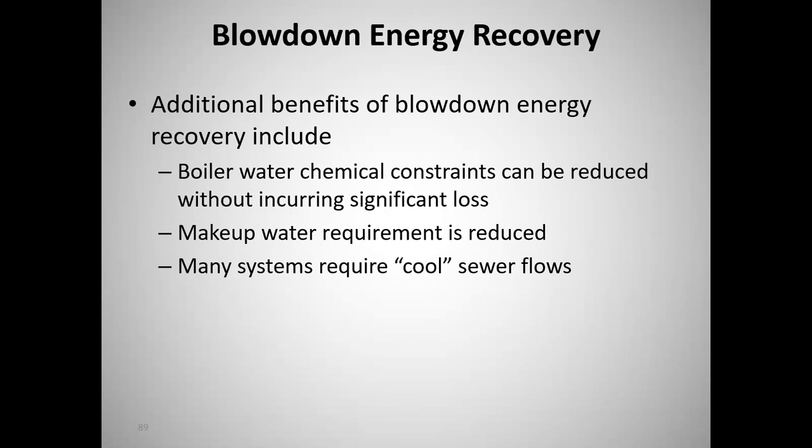Additional benefits from blowdown energy recovery include that boiler water chemical constraints can be reduced without incurring significant loss. That's less makeup water we have to add because of the recovered flash steam. That's pure water that stays in the system, so we have to do less chemical treatment. Makeup water requirement is reduced. Many systems require cool sewer flows. So if you're not recovering heat from this blowdown, it's very common to take just regular water that you're purchasing and blend it with that hot blowdown before you can put it down the sewer, because the water utility companies don't want 200-degree water going into the sewer.